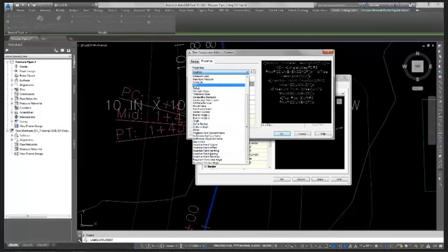So I have an SDR, the standard dimension ratio. Basically your outside diameter divided by your thickness gives you your SDR. If you didn't know that, I just found out what it was 2 hours ago. But for your fittings, I can use any of these columns in the content editor and use them in my labels just by changing the values in the content editor.